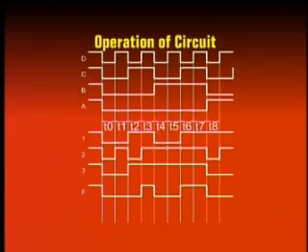At the interval T3, the input ABCD to the circuit is 0, 0, 1, 1. Now you have 2 adjacent ones, so the output of the circuit F should show a 1. Now let's have a look at the timing diagram. The outputs of OR gates 1, 2 and 3 are all ones, as can be seen in the timing diagram. The output F is also a 1.